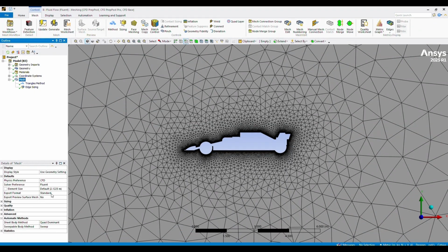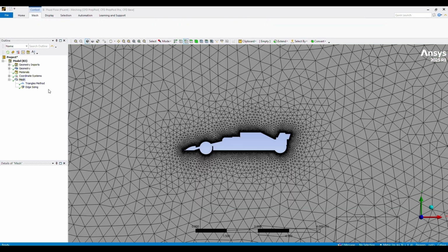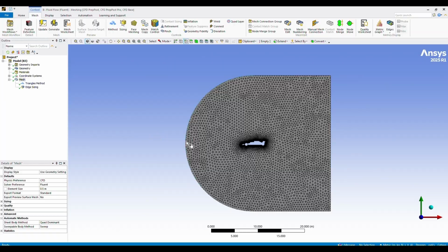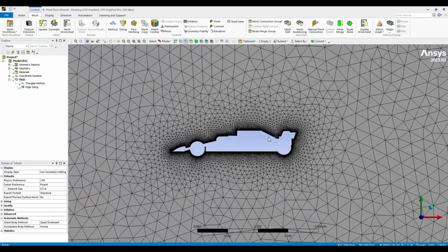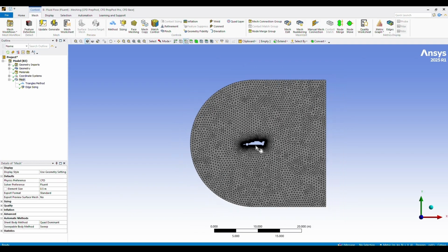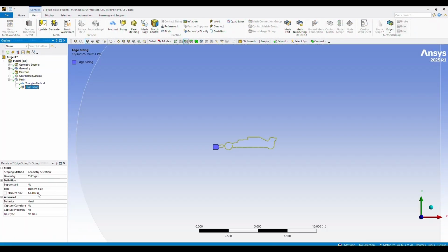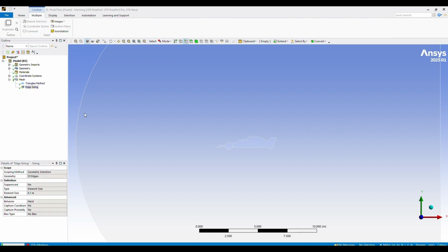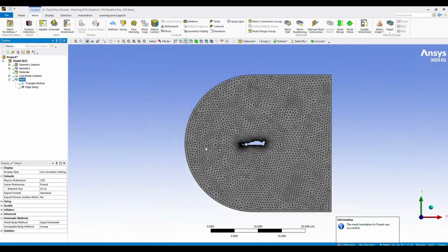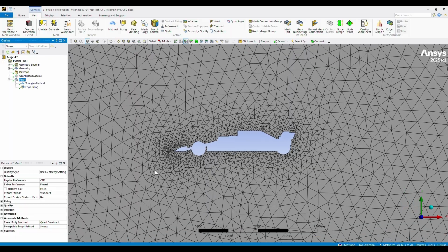Once it is done, I make the element size 0.5 to see how the mesh looks. Okay, this is the mesh that we are working on, making it not that fine. So this is what we are using for our second mesh analysis. So after this, it's done, and just to make it a not fine mesh, I kept the edge sizing at 0.1. So look, it's bigger, so we have a bigger section over there.